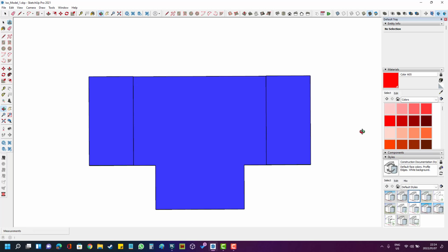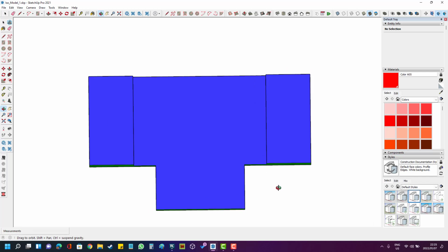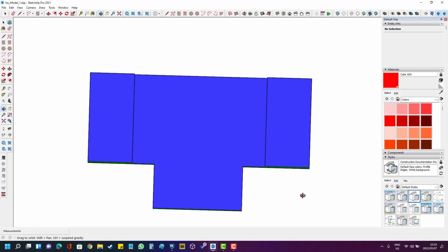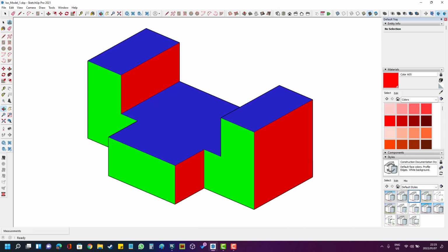We will always tilt the top view towards the front view to see what the layout of that top view will look like. And again, we will see the dark solid lines at the left and the right that represent this height difference that we have when we have tilted and done the transition from 3D to 2D. So there we have our 2D orthographic top view as we would see it when we draw it on paper. Good, and then we will just return it back to its normal state in 3D.